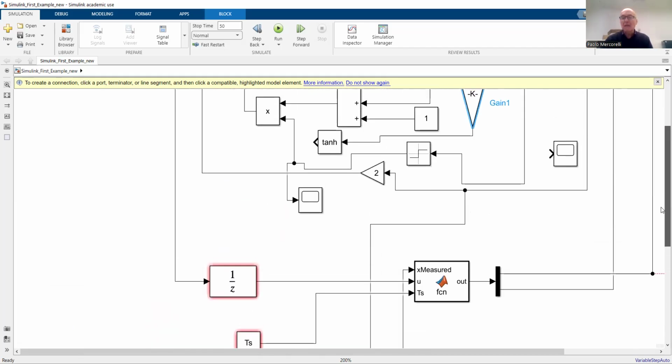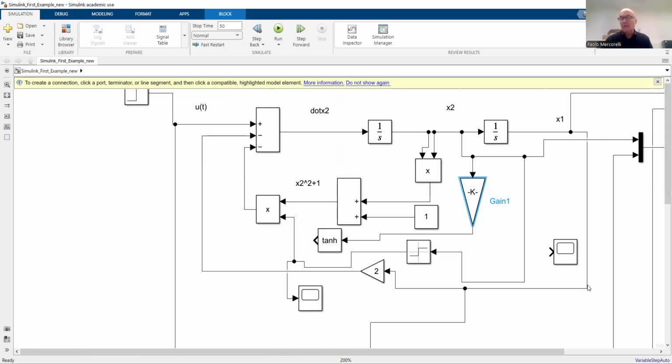In this example we measure the position, but the system is also observable thanks to x1, the presence of the spring, measuring x2. Why that? Conceptually it is easy. You can do it at home. Even if I measure x2, nevertheless, thanks to the presence of the spring, the information comes in x2 directly.